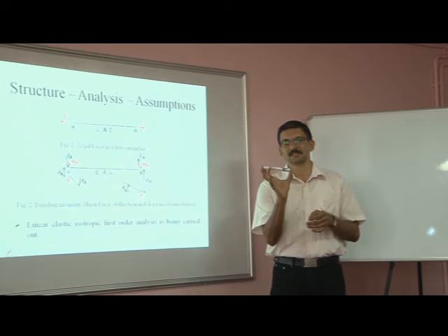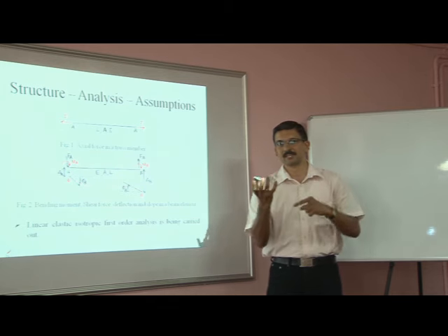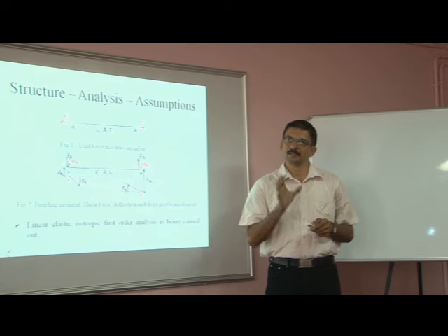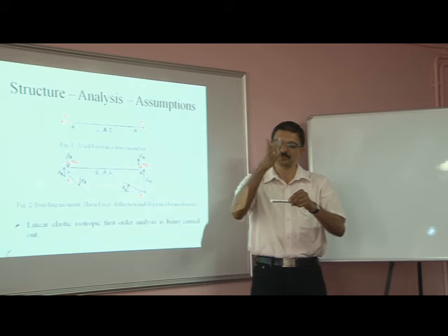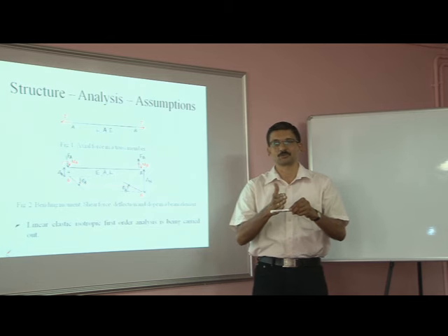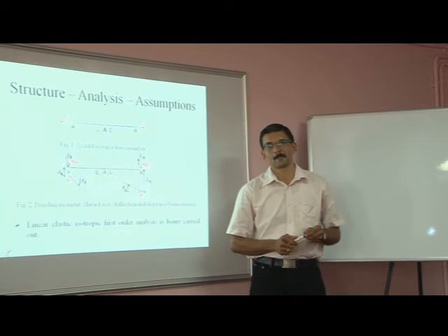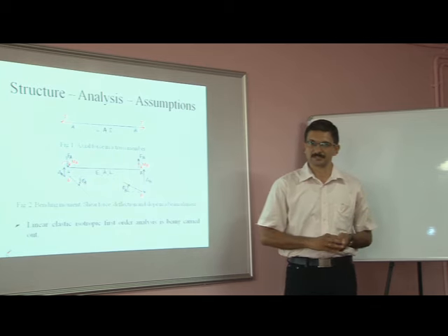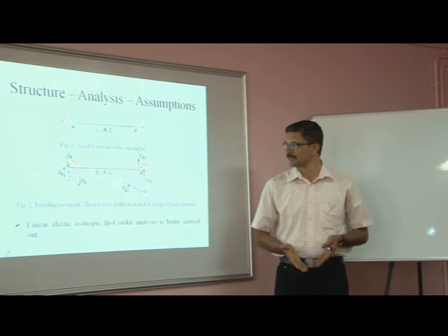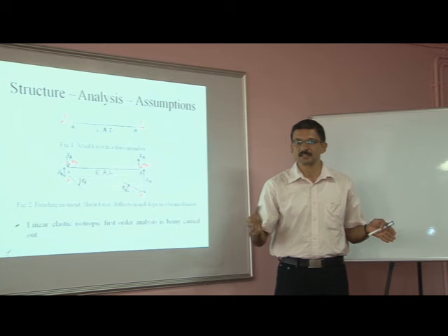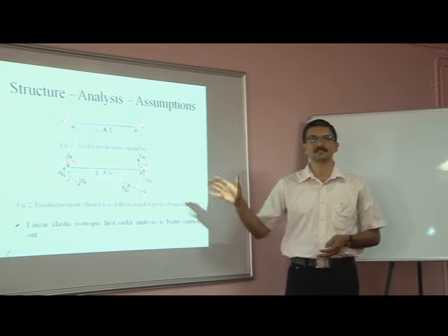In case of a beam-like structure, where we have transverse loads, the beam undergoes bending. That is why we call it a beam. The internal forces in a beam are bending moment, the moment which causes bending due to these transverse loads, and shear force. Shear force is a force which is trying to shear or break the beam. So essentially, for design of these big structures consisting of truss elements or beam elements, we are required to find out the axial forces, the bending moments, and the shear forces. And design is based on these internal forces.